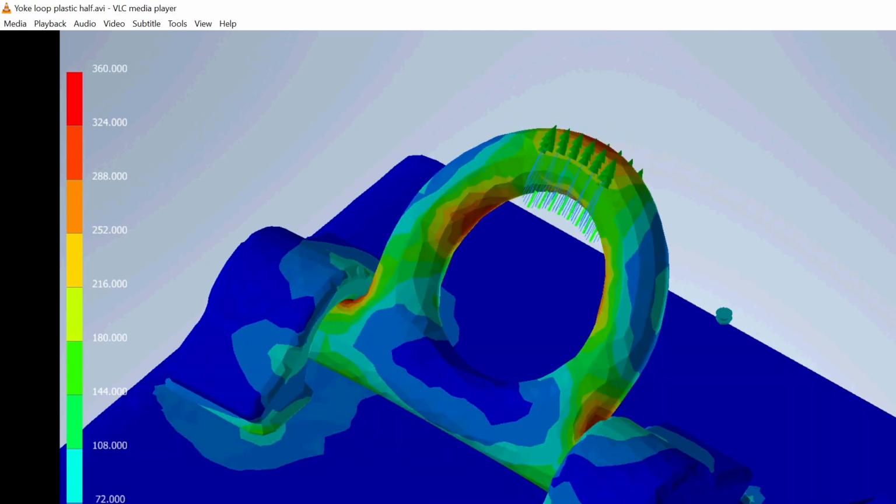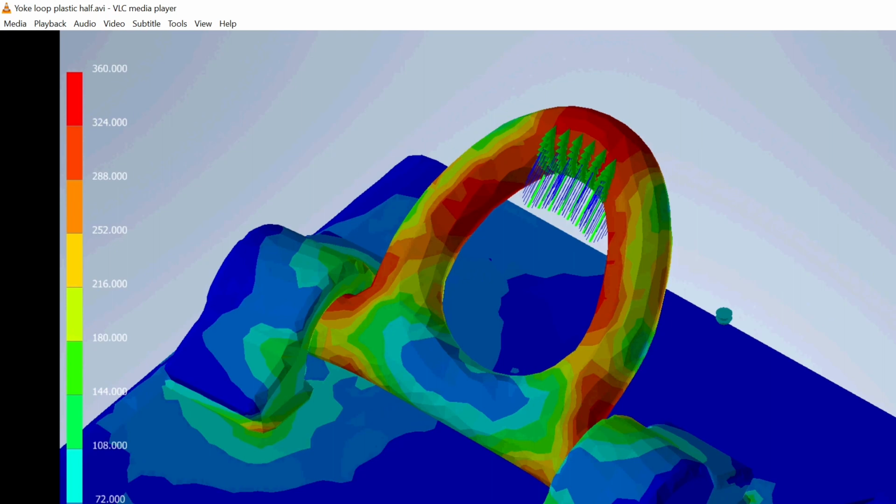Yeah, so this is a pretty interesting way of doing it because you are capable of modeling interfaces between solid bodies. These brackets here technically have a contact surface which is separating, so it's surface to surface contact being modeled, and these welds are very easy to draw in a package like Inventor or SolidWorks, and it's one way to look at it.